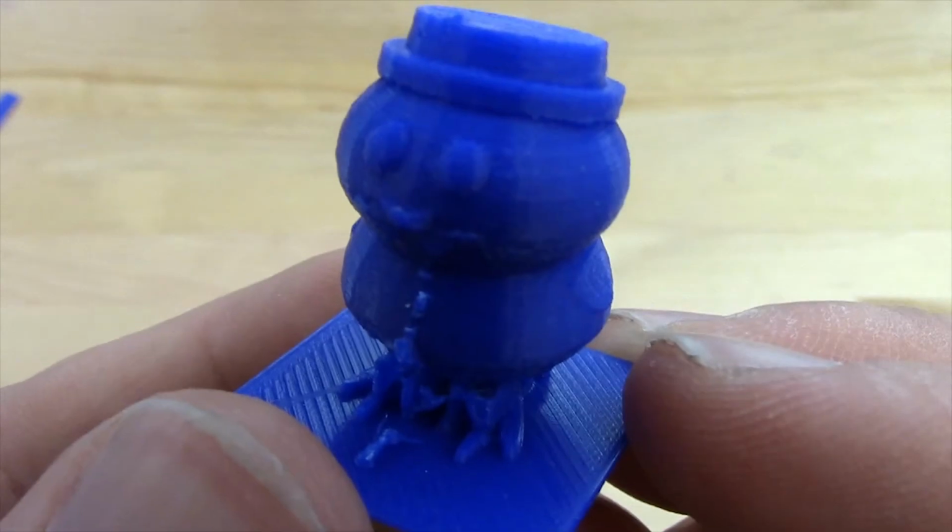Take a look at the printing material overview video, and you can see what it looks like to use no support material for this part. And although in that version the legs and feet come out much cleaner without support material surrounding them, the part itself has a little bit more distortion due to the lack of support material utilized.